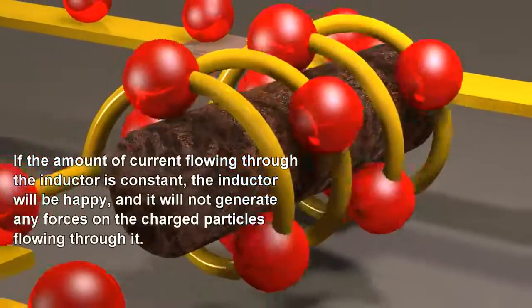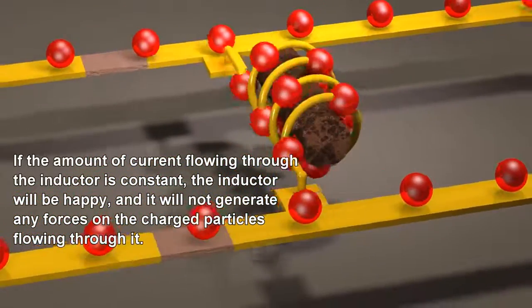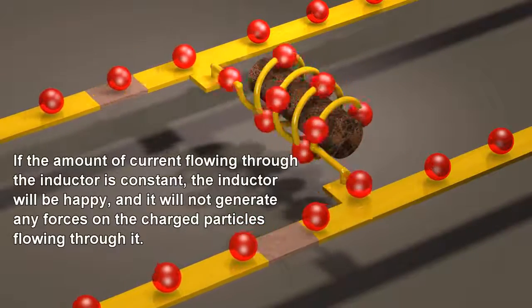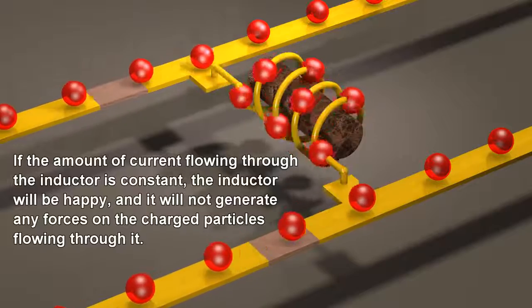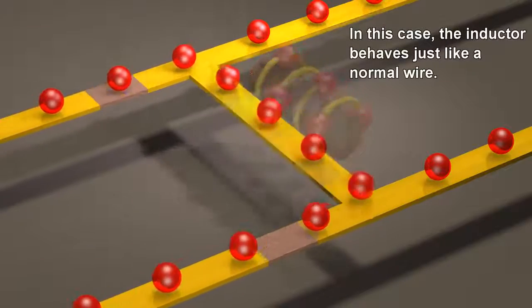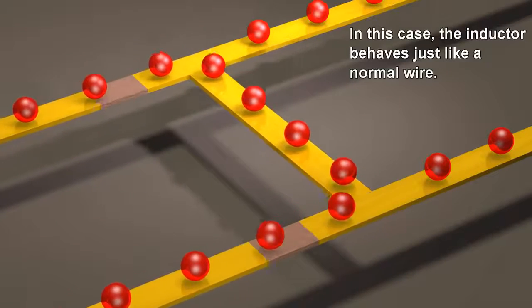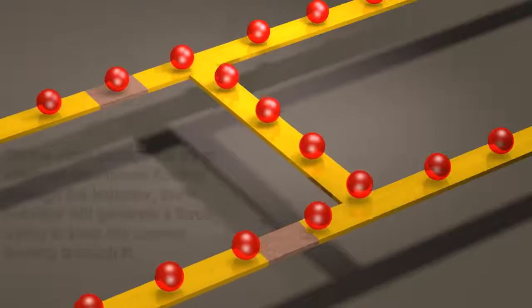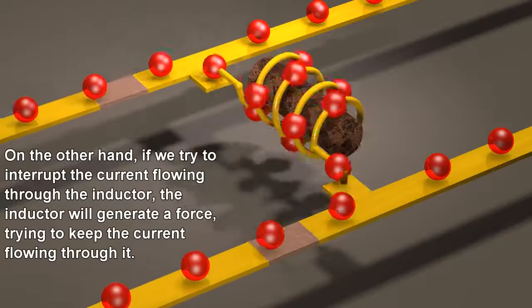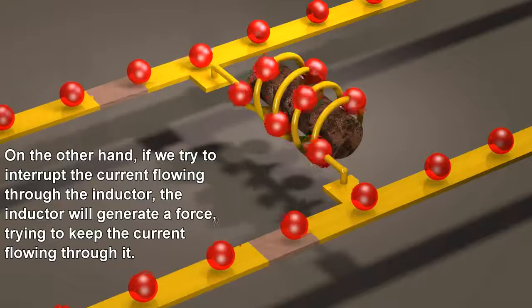If the amount of current flowing through the inductor is constant, the inductor will be happy and it will not generate any forces on the charged particles flowing through it. In this case, the inductor behaves just like a normal wire. On the other hand, if we try to interrupt the current, the inductor will generate a force, trying to keep the current flowing through it.